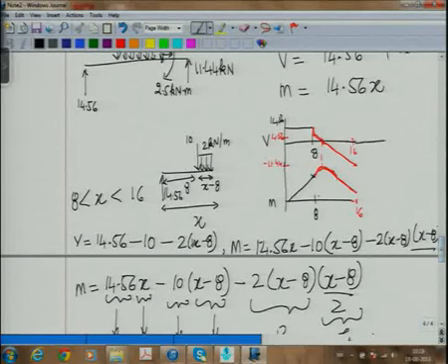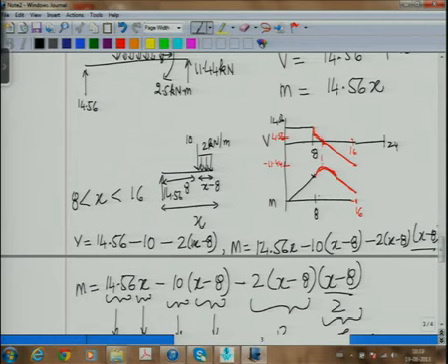So if we move from 16 to 24, the shear force, let us put a navy blue color to this, stays at minus 11.44. What happens in the bending moment diagram? First of all, there will be a jump. That is what I wanted to point out when I do the bending moment diagram, because at 16 there is a clockwise point moment of 2.5.